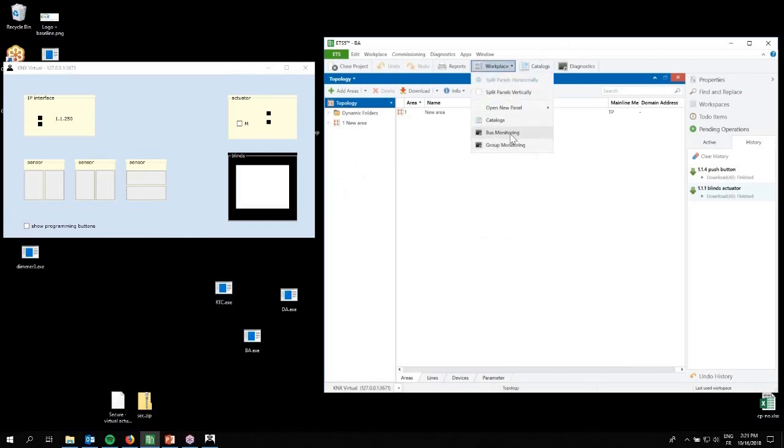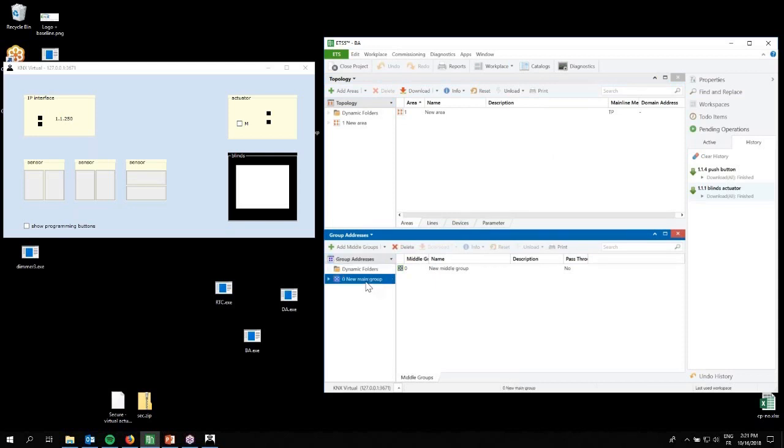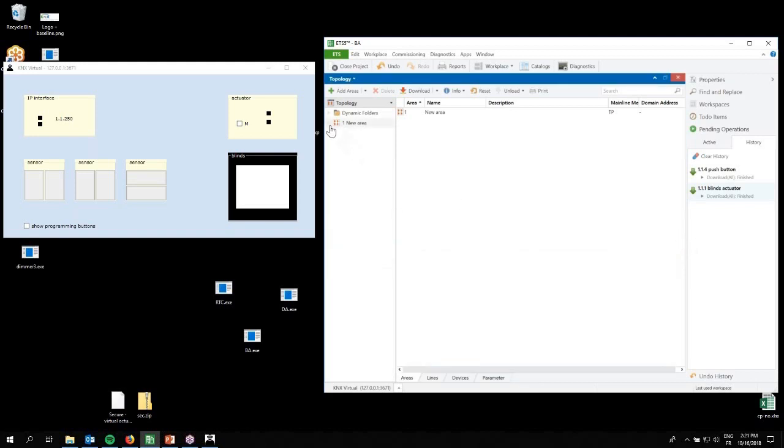I'll make sure I have no group addresses here. So group addresses, just delete whatever is there, so that I have a fresh project with no group addresses. Good. So what's here? Well, we have a blinds activator. We have two push buttons with vertical rockers, which I will not use. I will use this one with the horizontal rockers. Because what is in the activator?